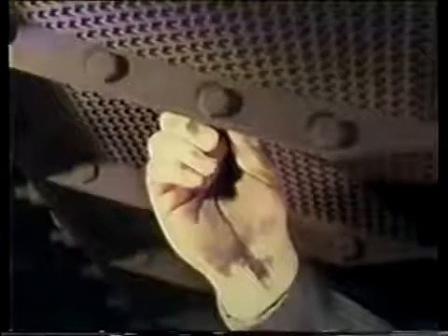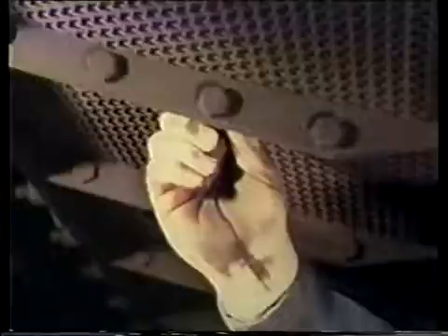Look for holes or cracks in any of the separator parts and make sure that attachment bolts are tight. Cyclone separators should be checked to see that they are positioned so steam flow will enter correctly. All parts should be held securely in place. There should be no broken studs or supports. Loose parts can bang around on the inside of a boiler and cause damage.